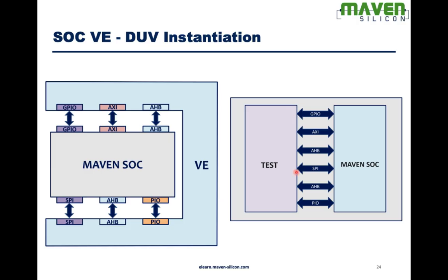And the Testbench will also have all the interfaces, and it will have the components like GPIO generator, GPIO driver, GPIO monitor, AXI generator, AXI driver, AXI monitor. So within Testbench, you need to create all these components, and you have to connect all these components with each interface, and you need to connect each interface with DUT interface. So there will be too many connections. There also we can think of applying interface. So in Testbench also we use interface to make the connections.